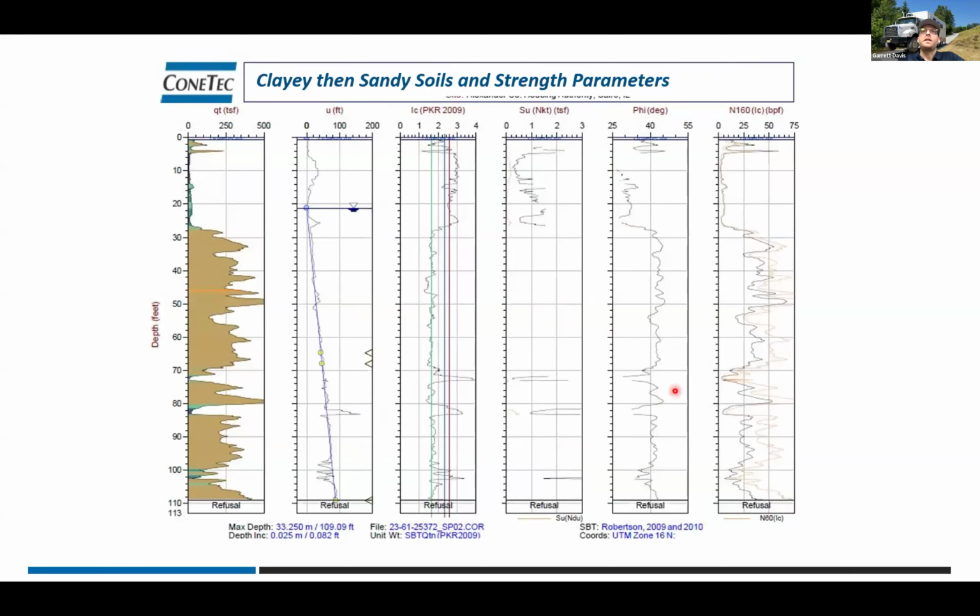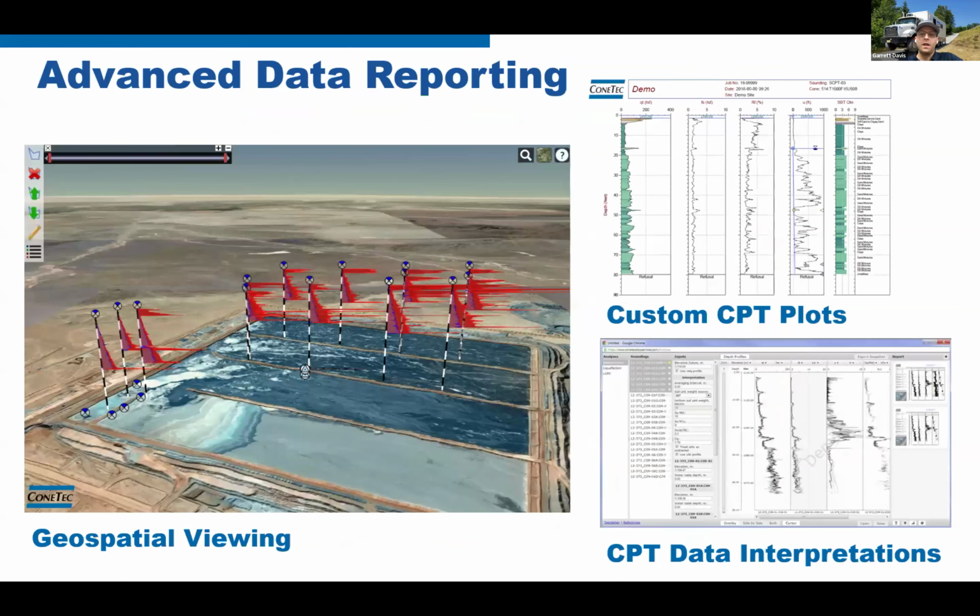This is also a great example of the ability of the cone penetrometer to advance through 40, 50 plus blow count material. Some of our cone penetrometers have the capacity to measure up to 1,000 or 1,500 bar, and other cones exist with much lower capacities that are used to classify more sensitive sites like lake sediment. So there's various ways you can report and play around with the CPT data once you've collected it. Use it in models, create your tailored plots, perform interpretations, etc.